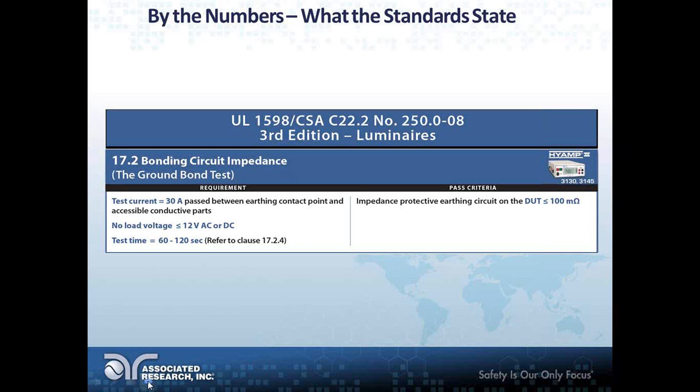Sometimes really 1 second isn't enough time. You want that circuit to heat up because obviously as you heat up the grounding circuit, you're going to get a higher resistance, and you want your worst case scenario here to make sure your product's safe.